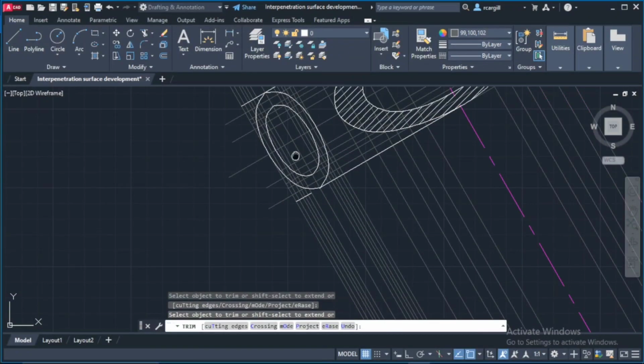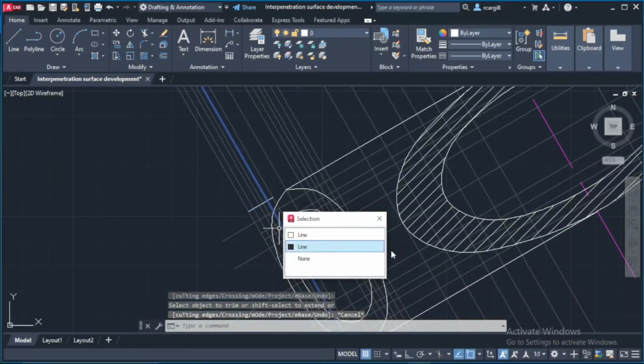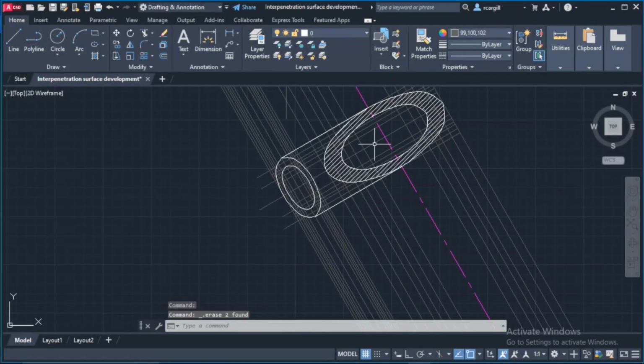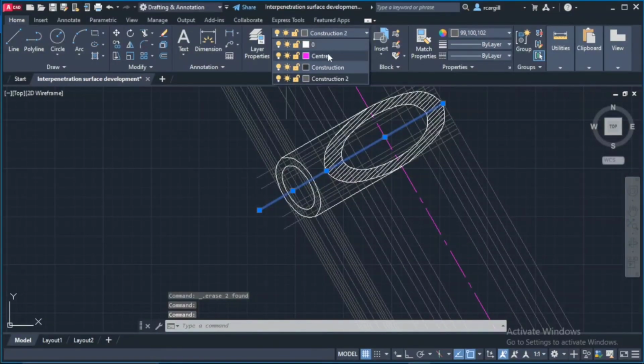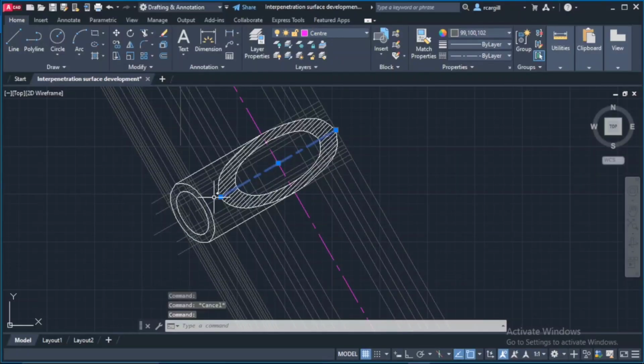From here, you're basically done with the drawing. You just need to put in a few center lines and dimensions and stuff. And you dimension the drawing the same way it's dimensioned in the question. So like this now, we'll change this to a center line. And actually, let me go by layer here.